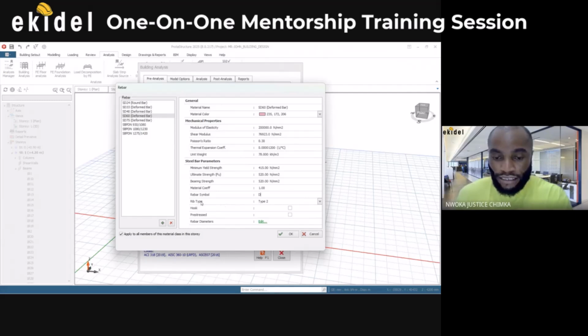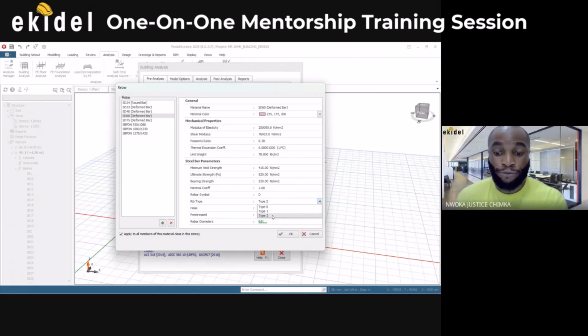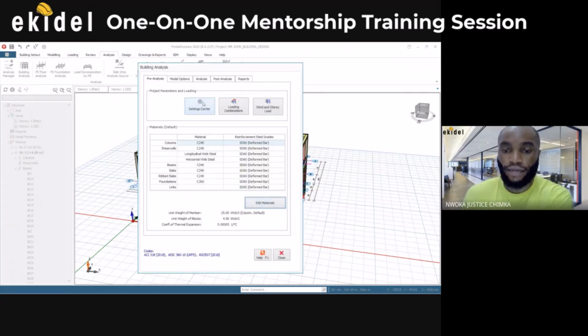Then here that's the rod type. You know that we have several rods, like smooth rod and all that. It's corrugated. Exactly, so that's type 2. That's a deformed rebar, corrugated. So once you have chosen all that, come here and say OK, and then everything will change, and then say final OK here.